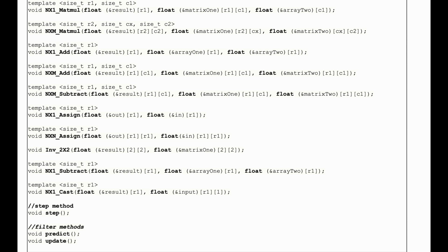Notice how I'm passing in the result at each time step. It's because I will pass everything by reference. I don't want these functions to return anything, and that is why I have a void over here. In RTOS applications, it is preferred to do that. It's preferred to not have methods return anything. So you have to define the result outside and then pass it in there. And now I will show you my system code where you will see how it's implemented.